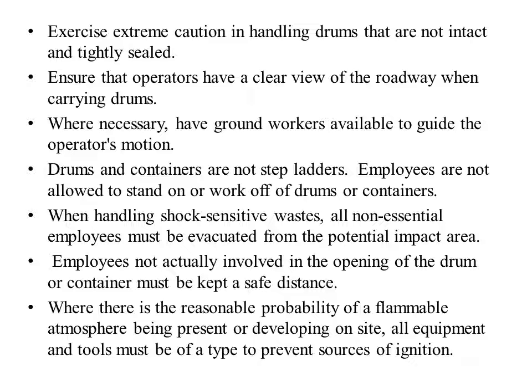So there are certain ways. If the container falls to the ground, then it may result in shock waves and some chemical reaction may take place, and this may result in explosion or catching fire. Therefore, in such cases, workers who are not needed for handling of drums should be evacuated from the potential impact area.